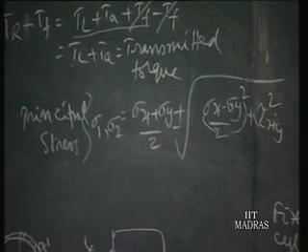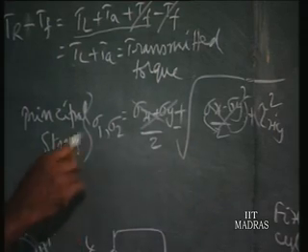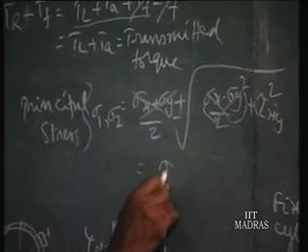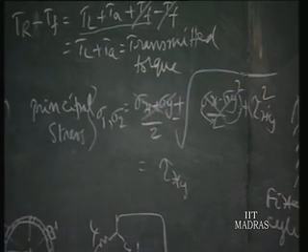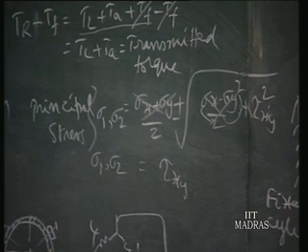In torque applications we do not have these coordinate stresses. So you find the principal stresses sigma 1, sigma 2 are equal to tau xy, because of the square root of a square. So that alone remains; the principal stress sigma 1, sigma 2 will be tau xy. That is the same as the shear stress, appearing as compressive or tensile stresses, and the angle at which it will be oriented is given by tan 2 phi.